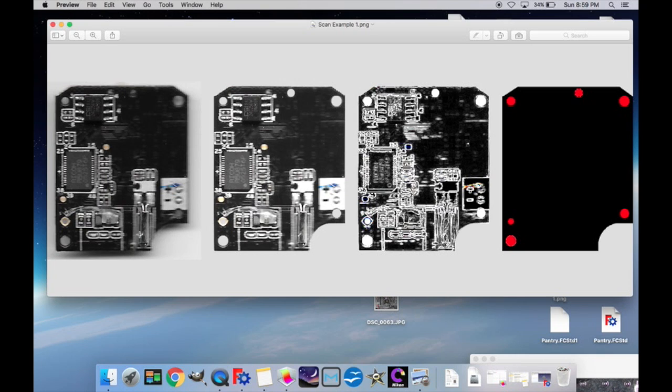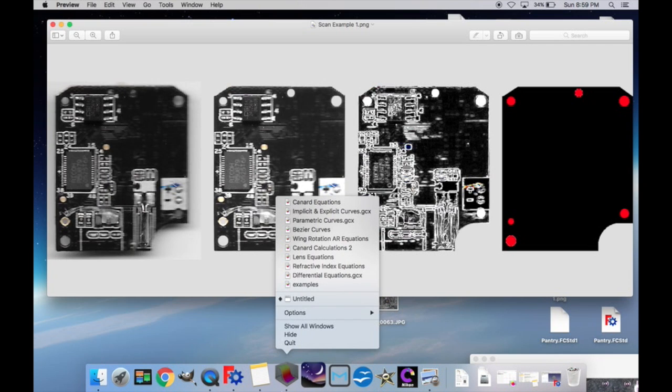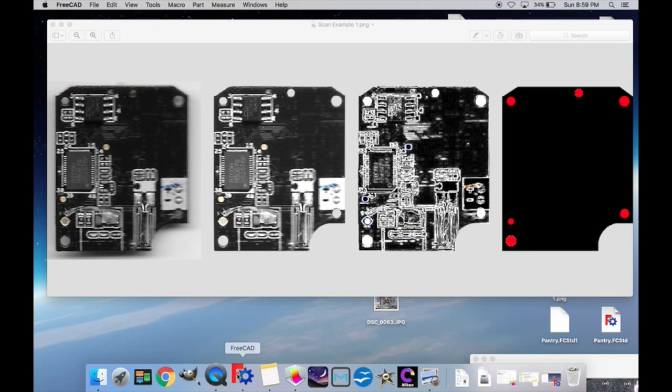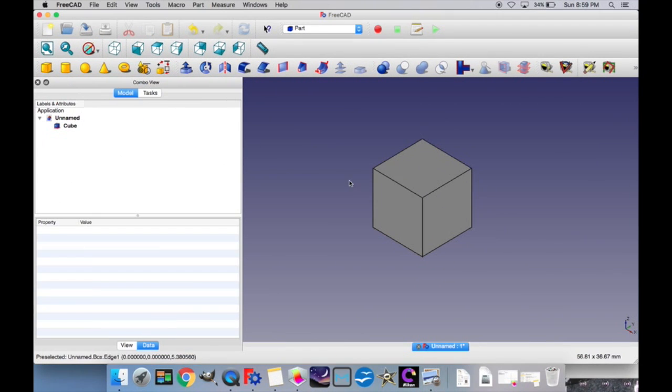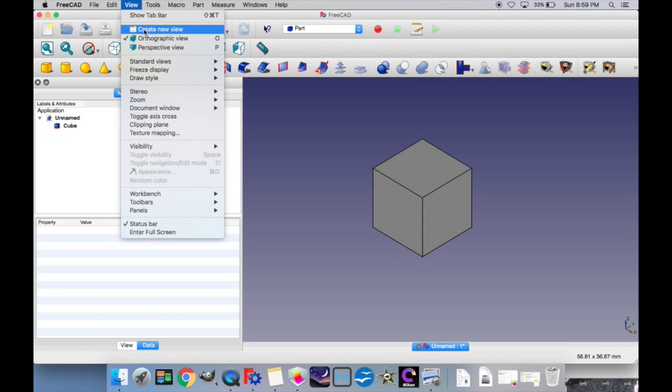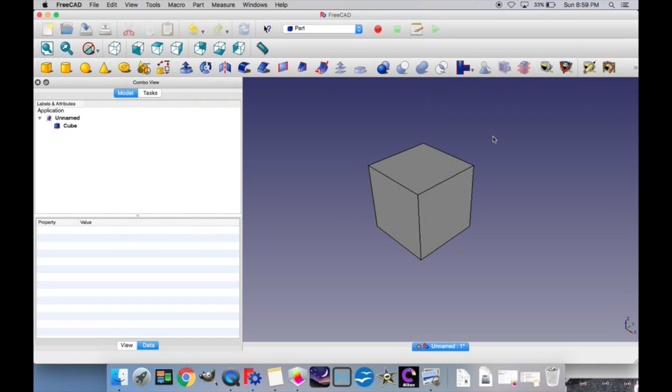One of the first things I want to talk about is it's difficult to use a normal camera or a phone camera or normal camera lens to capture an orthographic image of an object, and I'm going to go ahead and use just a cube in FreeCAD for my example here. So this is how we want the object to appear, but unfortunately most camera lenses are not telecentric. That is, they have an aperture within the lens itself instead of at infinity.